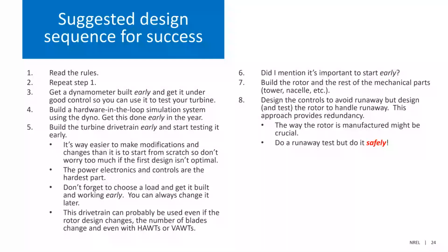If I were doing this, I would do this outside, a long distance from everybody. But another way to do it inside is to build a sturdy cage around it to contain all the parts. That's effectively the method we use in the wind tunnel, where the entire wind tunnel test section is surrounded by a half-inch of Lexan.